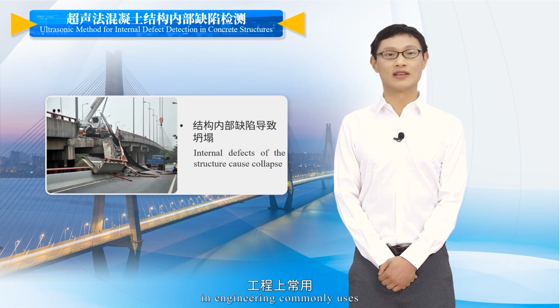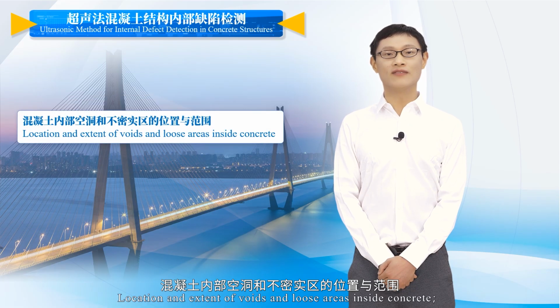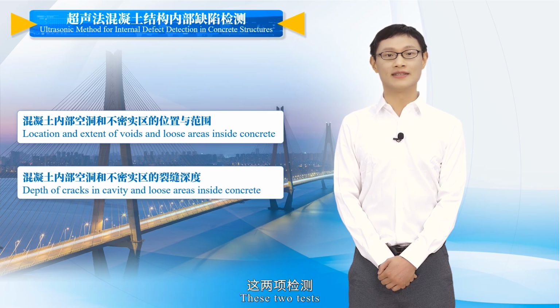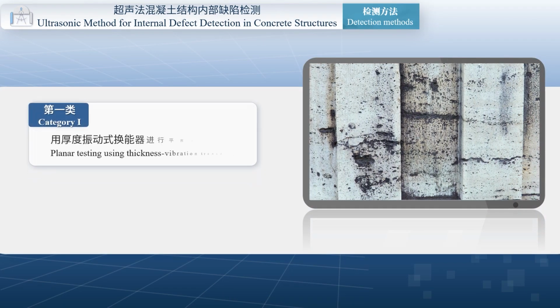In engineering, the ultrasonic method is commonly used for bridge concrete detection of internal defects in the structure. The main testing contents involved include the location and extent of voids and loose areas inside concrete, and crack depth. In this section, we will focus on explaining these two items.